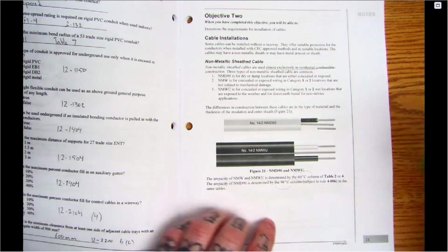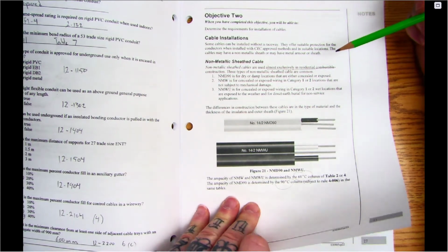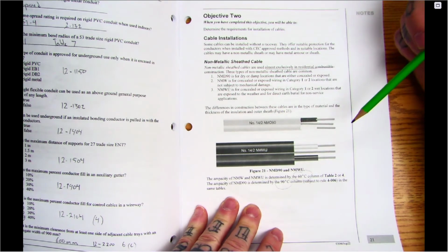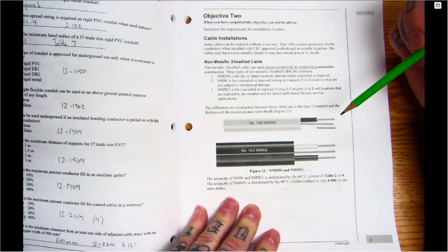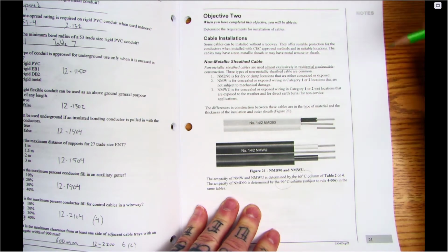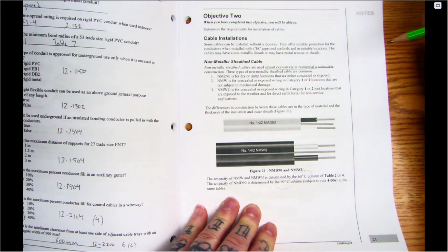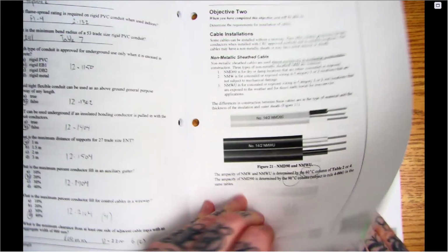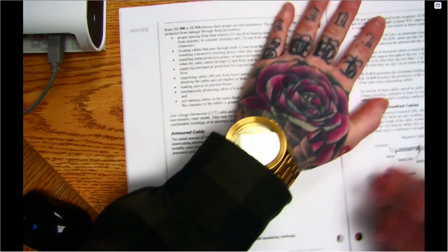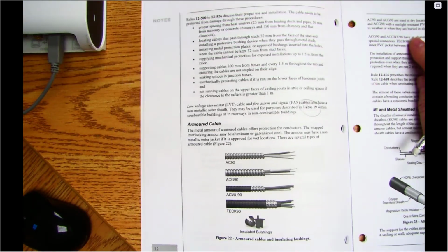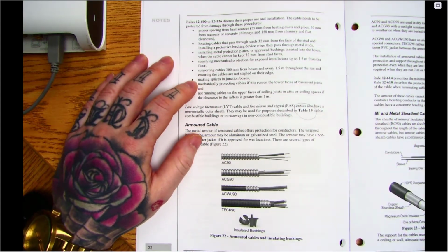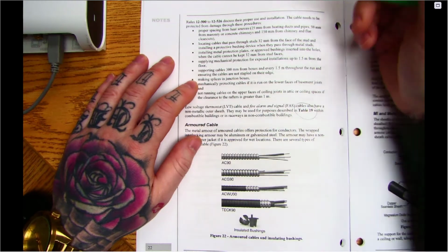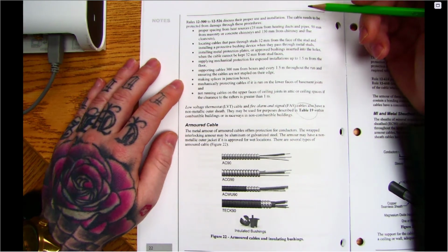NMD90 obviously is for 90. So watch that if you're doing a calculation where you have to potentially look at temperature terminations. If you're using NMW or NMWU, that's a 60 degree insulation. That is our Loomex. Usually, if you've done any residential, or even commercial with a wood construction office or something like that, you would pull NMD90 in that as well.